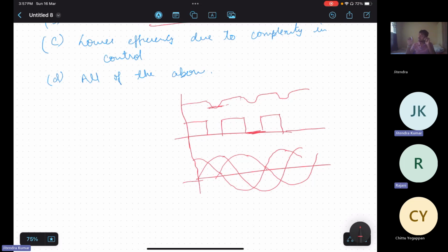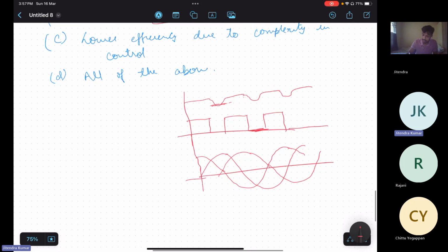So if you see the torque profile, it is very smooth compared to the BLDC operation, which we also call square wave operation or trapezoidal excitation, right? Trapezoidal excitation has a major issue related to cogging torque and harmonics in the machine. So that's why we prefer sinusoidal excitation.